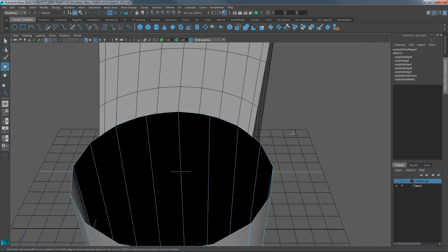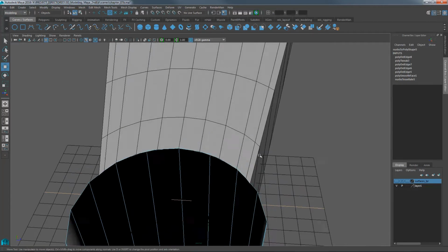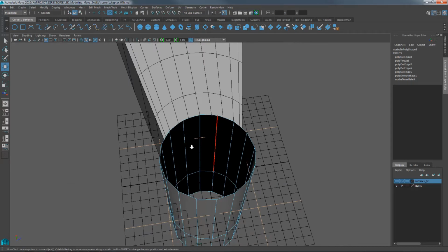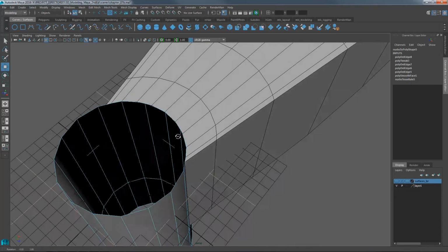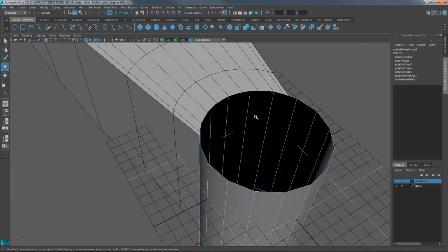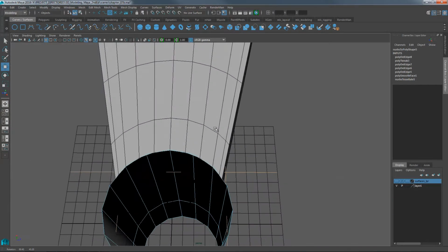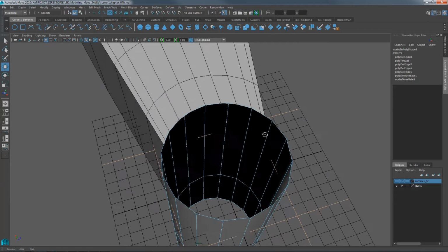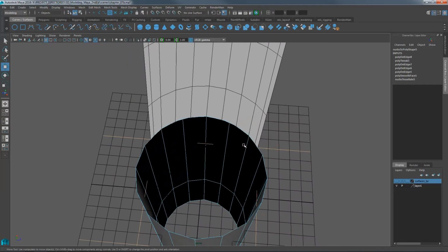Now let's take a look on the interior and see, do we satisfy the problem of having enough vertices here to support on the inside of the cylinder? And it looks like it does not, because I did not convert the original surface that was on the inside, creating this boundaried surface on the top. That's okay. Eventually this is all one piece of steel. We're going to fake that these things are welded together, the pipe and the plates. So I have basically 5 edges on the inside of the cylinder, and I have 11 edges that I need to connect to across the top.